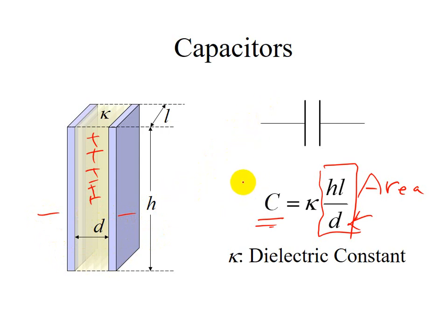But for the technology development, it looks like we are going to build capacitors as small as possible. So when you reduce the geometry factor here, that means your capacitance also tries to reduce. If you try to keep up with the capacitance at high volume, then you need to have high K dielectric materials.